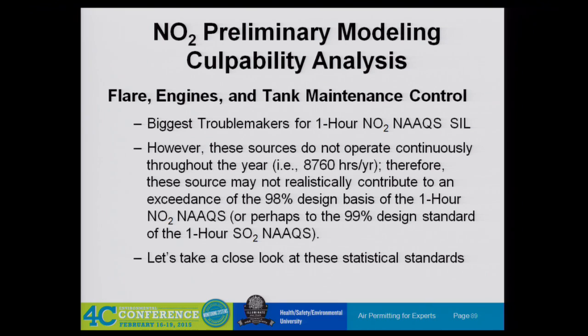And if the maintenance emissions were higher than the routine, I mean, you're not going to be doing both at once, right? So if your routine emissions are higher, that's your worst case, without any doubt. If your maintenance emissions turned out to be higher, I would ask myself, how many hours a year do I do these maintenance emissions? And can I make them qualify under this intermittent EPA policy? And if I can't throw them out altogether, are the hours certainly less than 500, maybe less than 120 or so, but however many hours it is, can I make it fit under my intermittent policy and annualize those? And then are they less than my routine emissions? And then I'd flop all the way back and say, you know what, I've determined that my routine emissions are my worst case hour. And that's all I'm going to model.